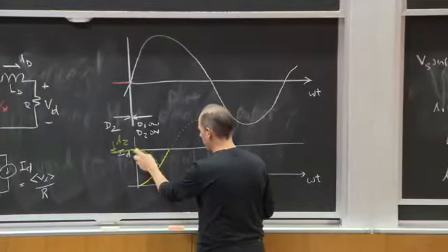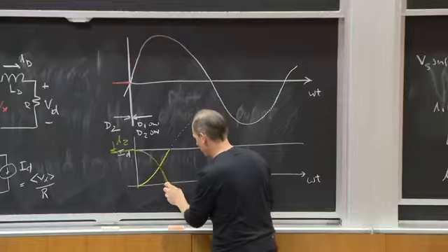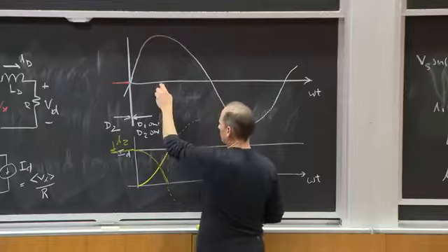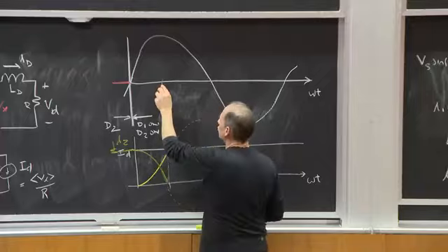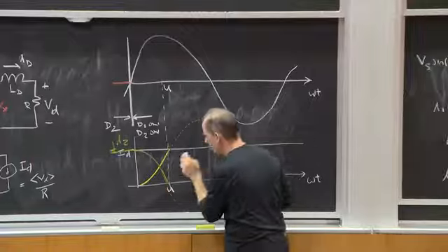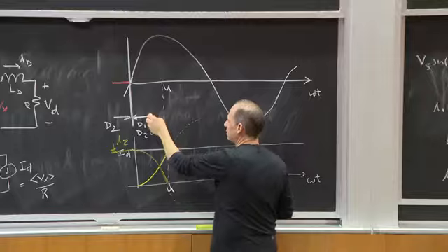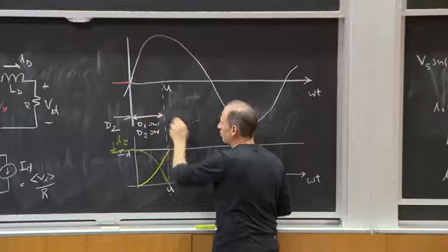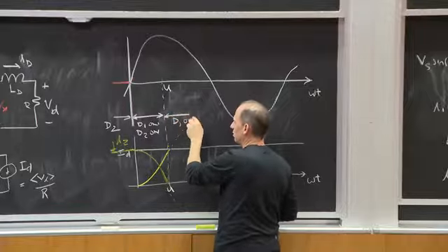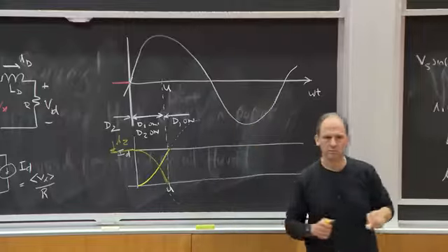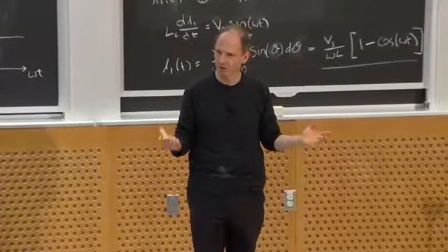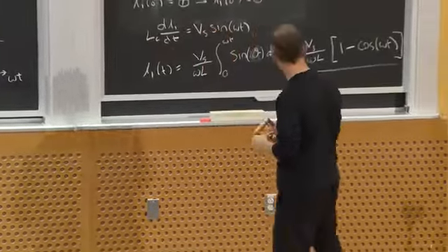So I'm going to hit some point here, where I'm going to call this sometime u, omega t is equal to u, where D2 is going to turn off, and maybe then I'll only have D1 on. Does that make sense, everybody? Because otherwise he would have a negative current in him, right? And it's my kind of third assumption.